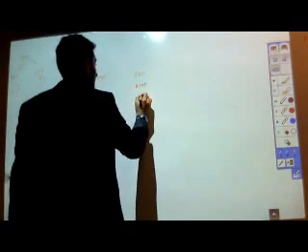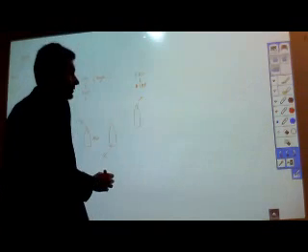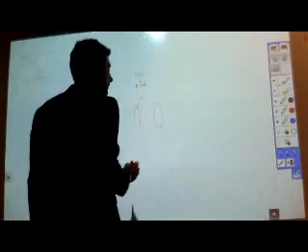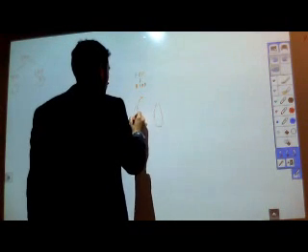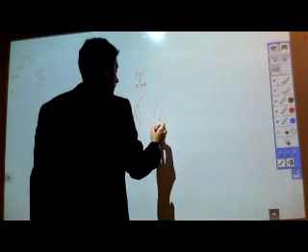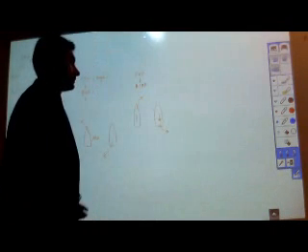This will be completely opposite again on a fixed pitch left-handed propeller. When your vessel is going to go ahead, you're going to go to starboard, and when your vessel is then going to come astern, the stern is going to go to starboard.